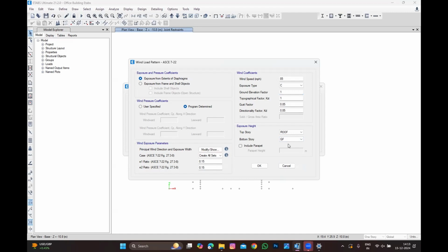Seismic is not like that. Seismic, you need to consider everything. Parapet is interesting. Parapet is up to the contractor, and if the designer has experience, he can decide. Up to 1.2, 1.5 meters. Most of the contractors will go for block wall, right? If you decided even for 1.2 to go for concrete wall, then you have to consider it.